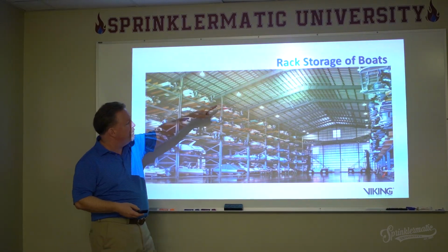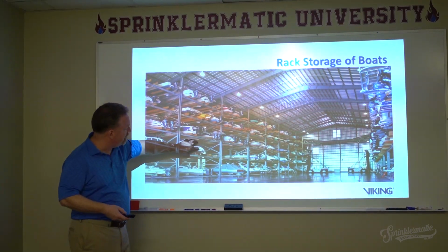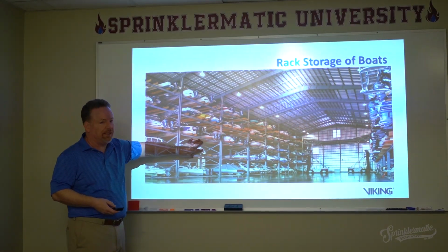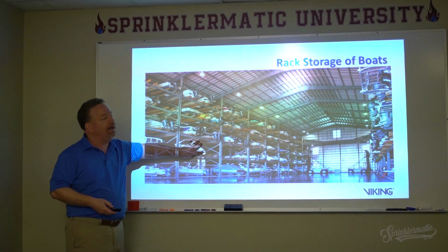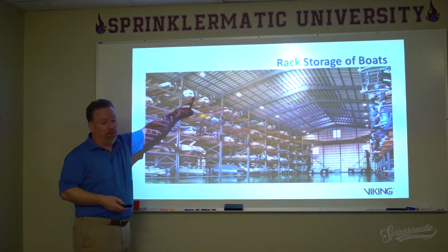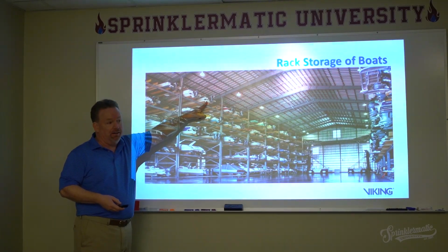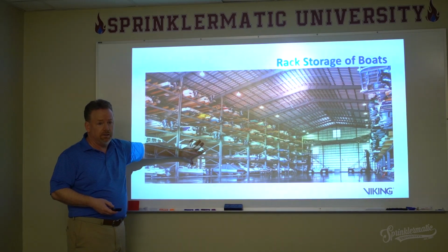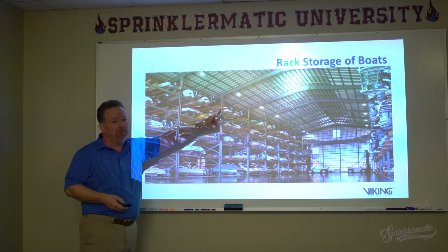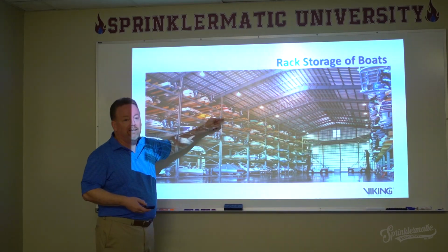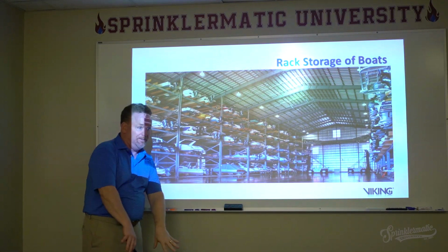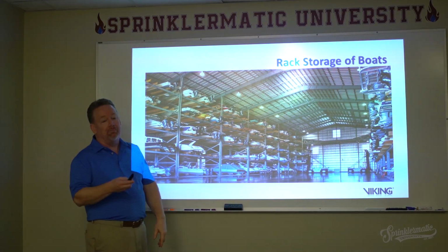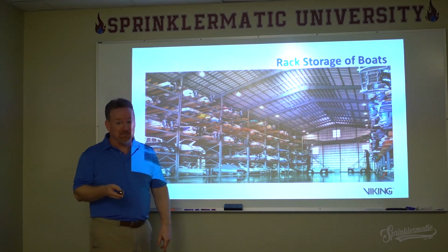The big challenge with putting sprinklers up here is, if I get a fire in my boat here, what happens? All that water comes out of the ceiling, and where does it go? In the boat. Yeah, it goes in the boat. It goes in this boat in particular, and that boat there, and it gets all collected. It's a highly shielded fire also. And then, okay, so let's fill a couple of boats up with water on these racks. Now what happens? It collapses. The whole thing collapses, okay? So once again, you're on your own when it comes to these.